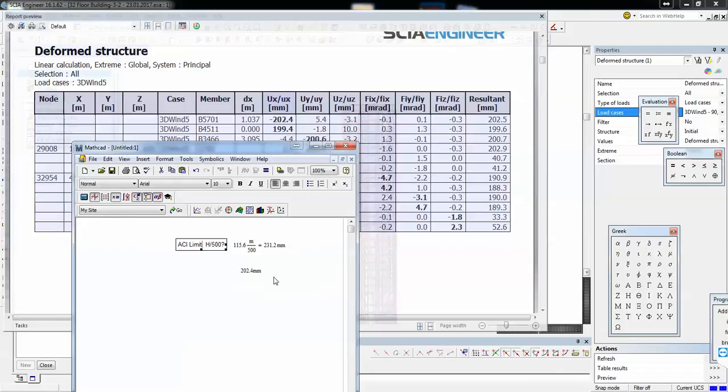I don't think the Eurocode. What about Eurocode? No, the Eurocode doesn't have this approach. The Eurocode will have a rotation per level, which we'll do together. So this is a limit in the American standard, but it's plausible. The way we got here is pretty much the same. For Eurocode, we don't have a limit for the top of the building. We have a limit for each floor, which we will discuss.